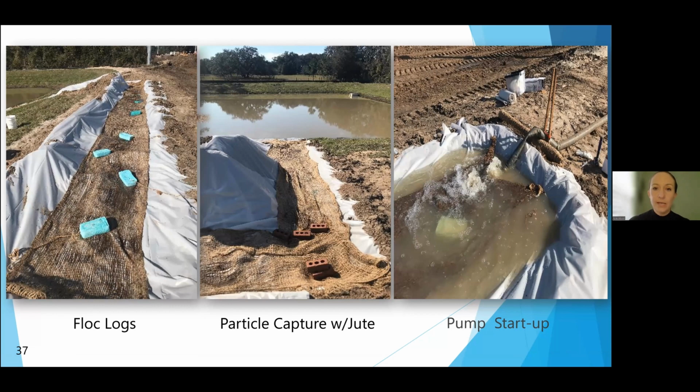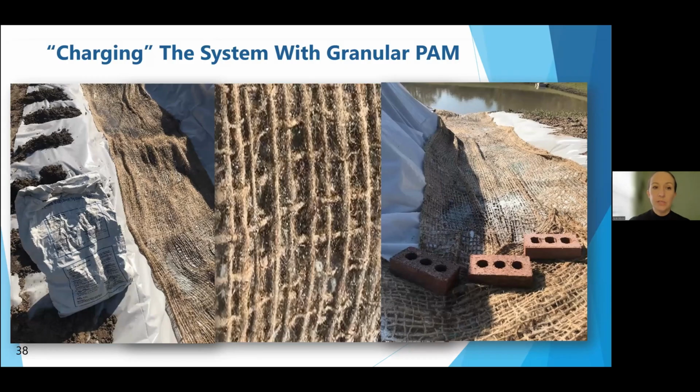As I mentioned, if we want the lowest clarity, it typically uses a combination of both the logs and the powder. The powder is great for water treatment because it has a lot more surface area, so it can give quicker results in terms of that flocculation reaction. Using them together is a really good benefit. So this one, we use both the powders and the logs in the channel.